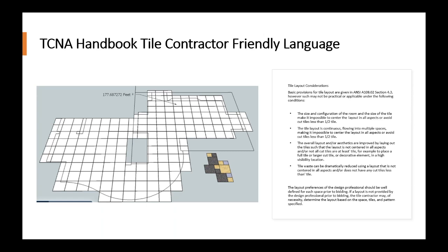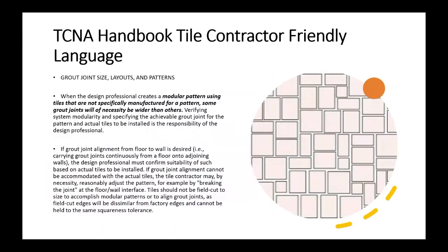If you start getting questioned about centering and things like that, use this document to your advantage. It's in the tile layout considerations in the front part of the TCNA handbook. Also, joint size, layouts, and patterns. Very, very important part of the front part of that handbook as well. This states when a design professional creates a modular pattern using tiles that are not specifically manufactured to be in a pattern.